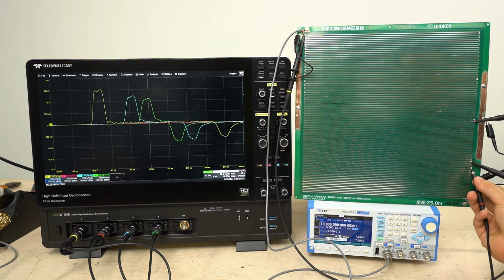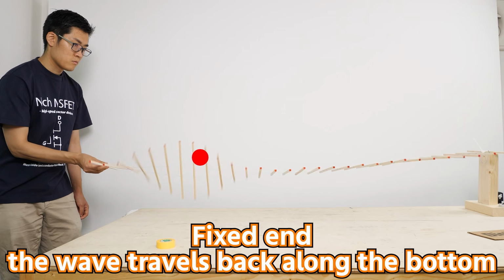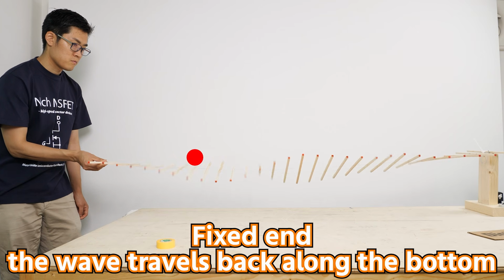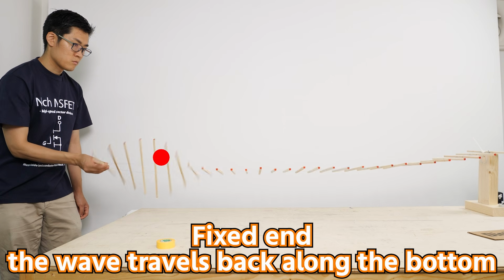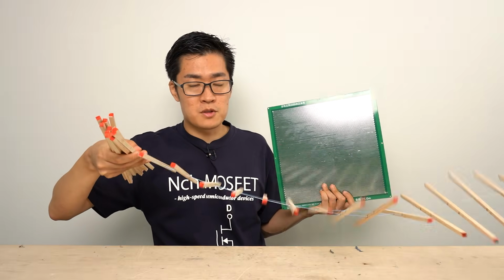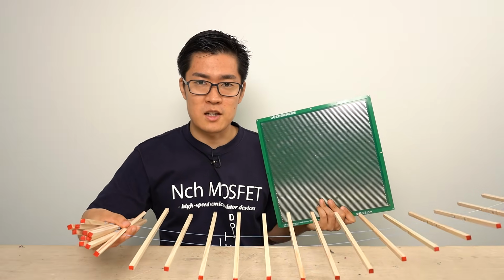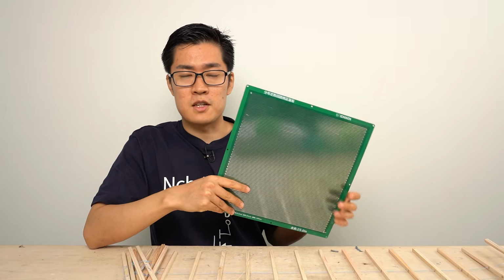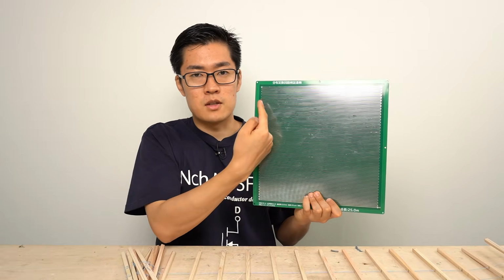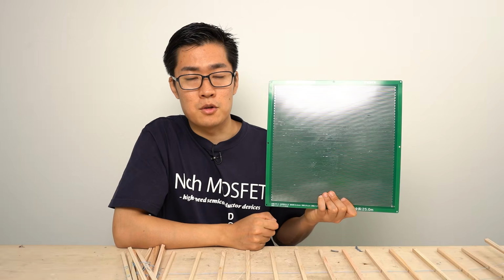Pretty interesting. I mentioned that the shorted end of the circuit corresponds to the fixed terminal of the wave machine, and that's exactly right. When a positive pulse is applied, it reflects off the shorted end and comes back as a negative wave. It behaves just like on the wave machine. I've shown that the way waves travel in electrical circuits is essentially the same as the way physical waves propagate through a medium. There aren't many demonstrations using a wave machine, but in electrical circuits we have something called impedance matching. When the medium changes while a voltage wave is traveling, the reflection and transmission of the wave also change.